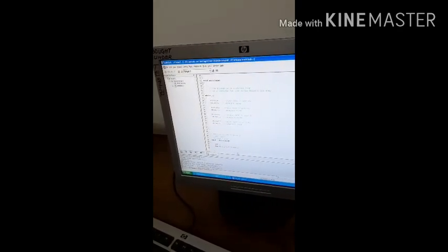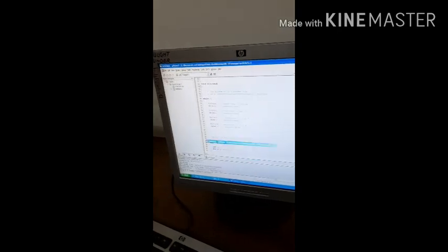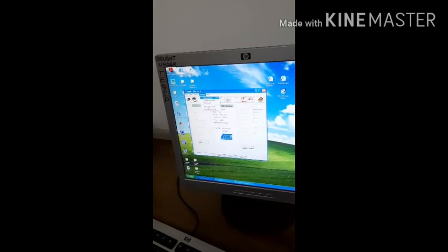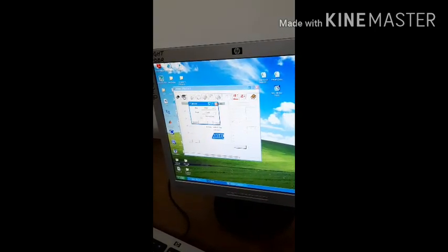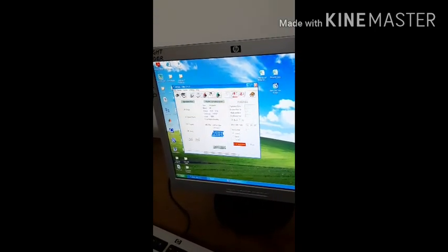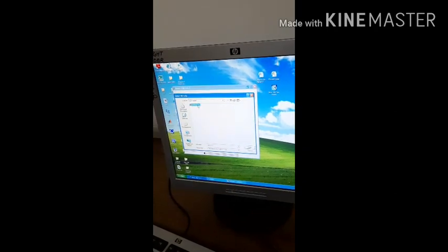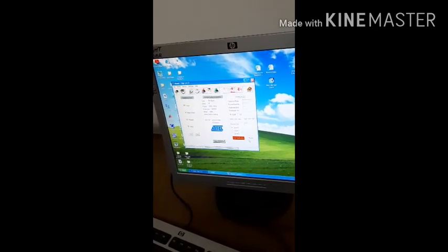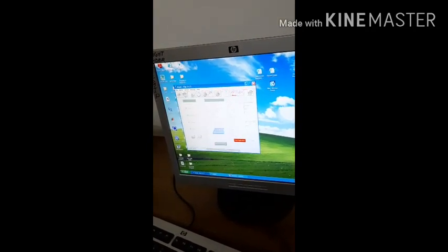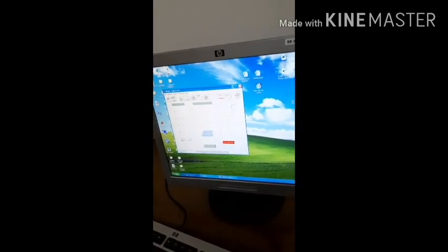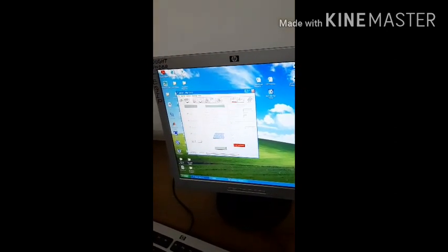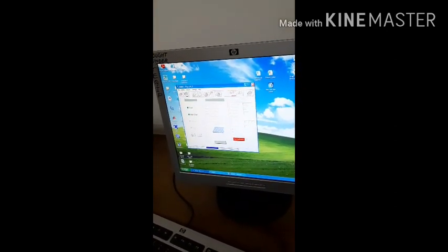So I have created the hex file again as I did earlier. Now I am going to FLIP settings, communication, RS232, so connect. So now I have connected the same file. Now I will be burning it into your microcontroller after making the change in the delay. So now I will run it. Once I run it: erasing, then blank check, then programming, then verification.